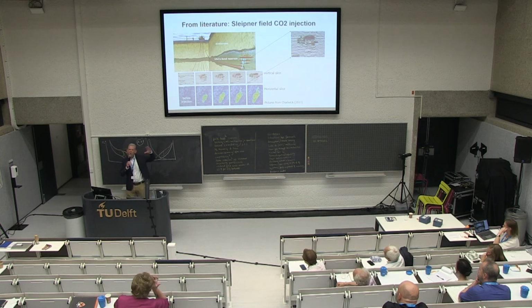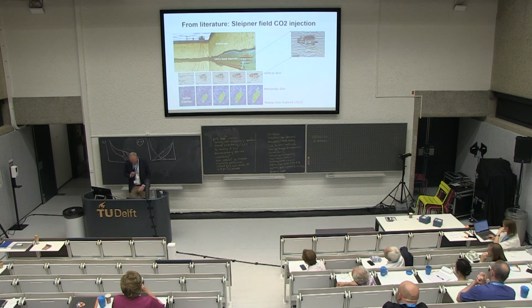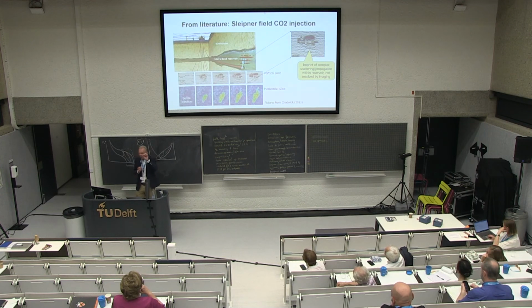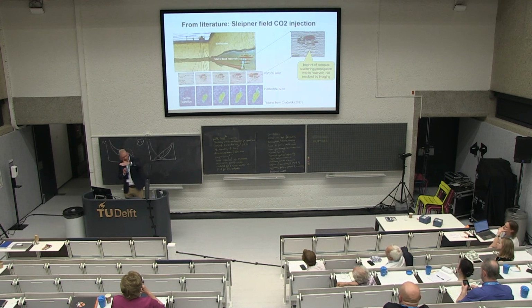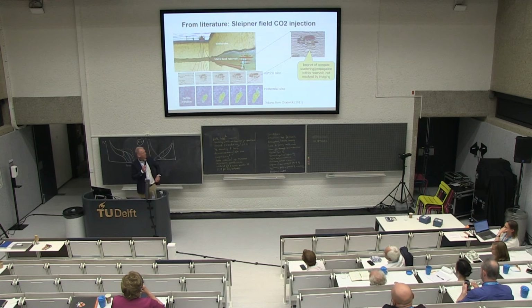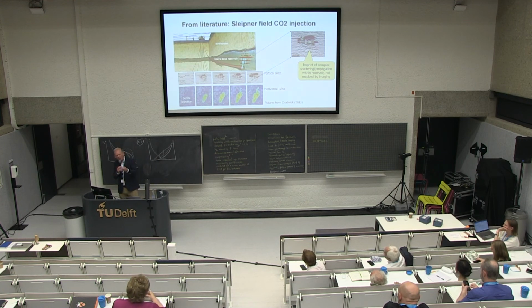That's, you might say, that's the context. But then the next step is really to dive into that and say, well, okay, in this pixel here, what is there? So if you look at one pixel of the image, when you zoom in there, then we can expound on that and then talk about, for example, angle-dependent reflection properties. And that is a key information that can be combined with the actual rock properties that you would have. First of all, elastic properties, so the bulk modulus, density, etc. But finally, you would like to link it to rock type or lithotype, etc. And to make that step, you really need borehole information. The well log information is crucial there.